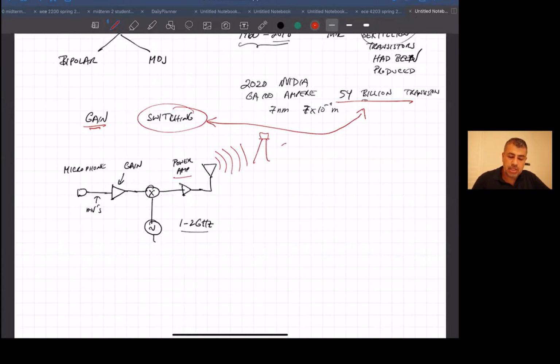base station or something. And then on the receiving side, let's say you've got the receiver. So now somebody is receiving your call. The first thing you have is a low noise amplifier, because again, the signal from the base station to you, you could be pretty far from it. So you could be in the microvolts when you receive this signal from the base station. When you're close, it's going to be higher. It's a very high dynamic range type of thing, but it could be a very small signal.